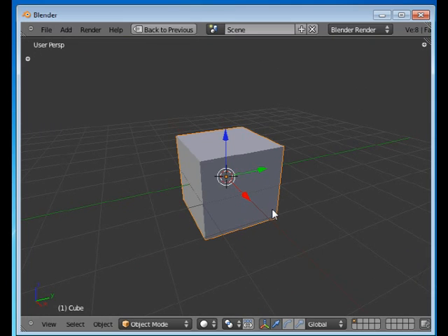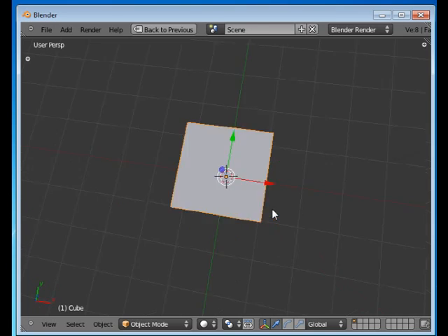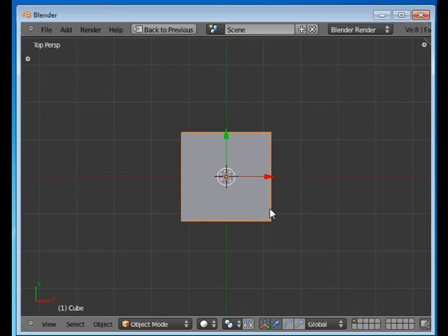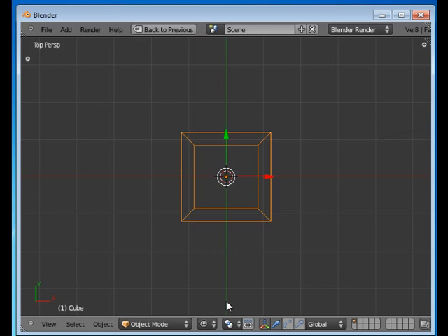To further demonstrate this, we'll switch to the top view. You do that by pressing number 7 on the num keypad. So now we're looking at this cube from the top. I'll change to the wireframe mode, and we can see how there is a vanishing point here. And it will also matter where I am relative to this cube, what it looks like.